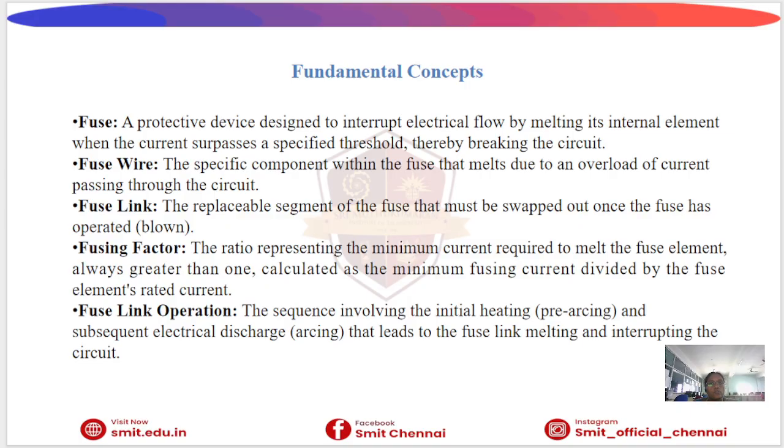Fusing factor: the ratio of minimum fusing current to rated current. Fuse operation includes heating of the fuse element and arc formation before the circuit is interrupted. These concepts help us understand how fuse protection works.